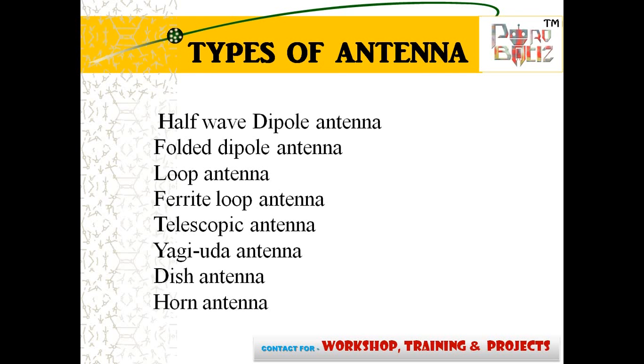Folded dipole antenna. The folded dipole is a single antenna, but it consists of two elements. The first element is fed directly, while the second is coupled inductively at the ends. If elements of unequal diameters are used, transformation ratios from 1.5 to 25 are practicable, and if greater ratios are required, more arms can be used.